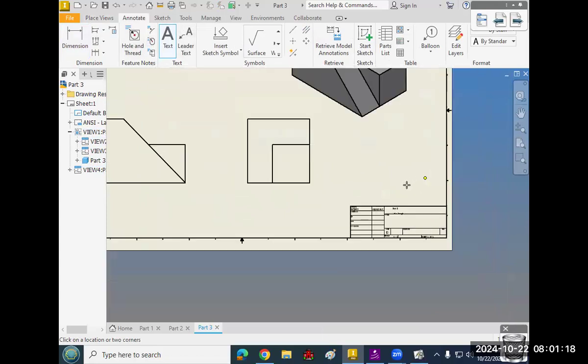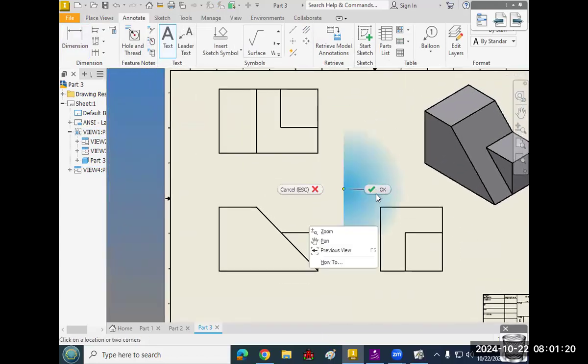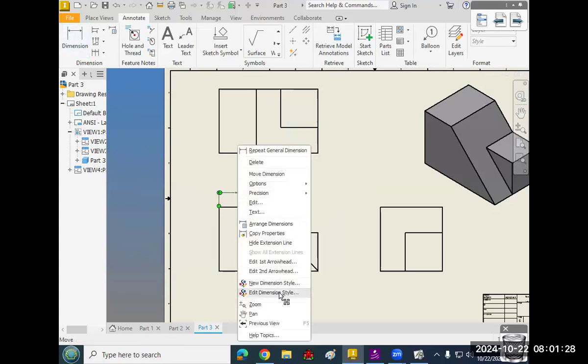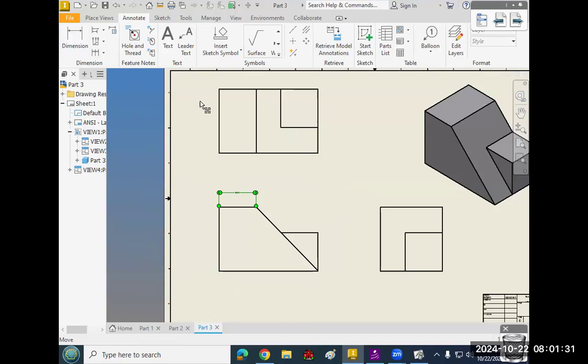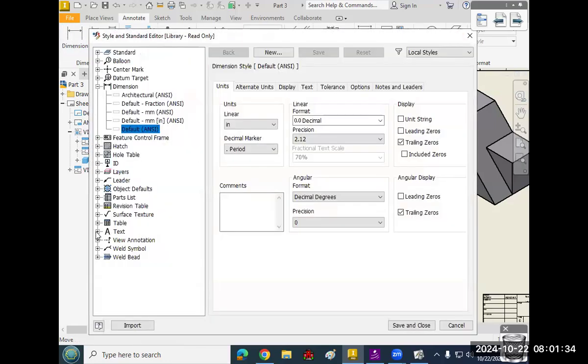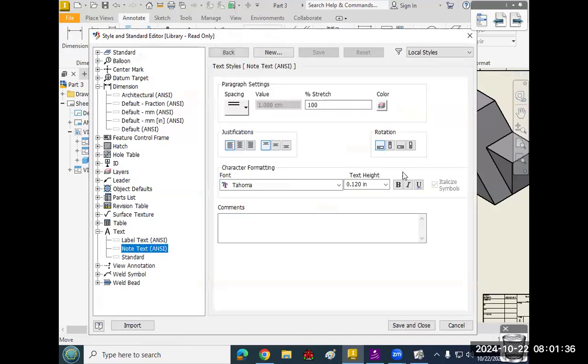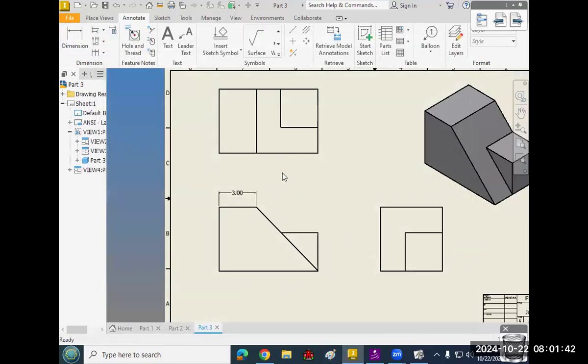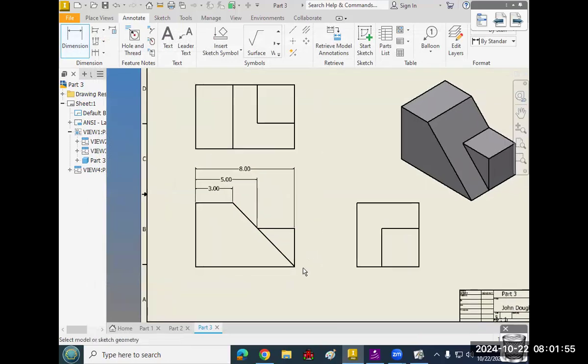Okay, and we can get going. With dimension, the first thing that happens is this, which is what we want. It goes to a contour, doesn't cross over, it's beautiful. It's as good as it gets. Then working left to right, the next thing is the distance to this notch, which is good here. The only other width is total width. Fantastic.